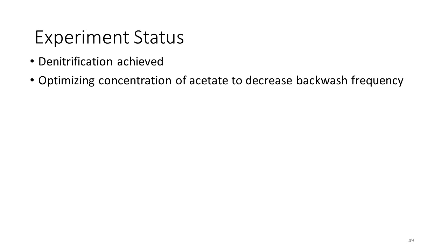What concentrations of geosmin were you using? I'm spiking with 750 nanograms per liter. And so did you allow the biomass to acclimate to the geosmin, because it oftentimes shows an acclimation period? No, just acclimate to using SMPs. So part of the lack of removal could be because the community hasn't adjusted itself to utilizing that low level of geosmin.